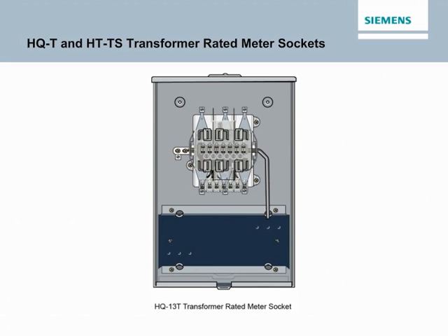All sockets are equipped with a 200% rated clamping jaw lever bypass. A removable bypass handle is available as an option. With the handle removed, a solid cover can be placed on the box with the bypass closed when it's necessary to remove the meter for in-shop repair or testing.